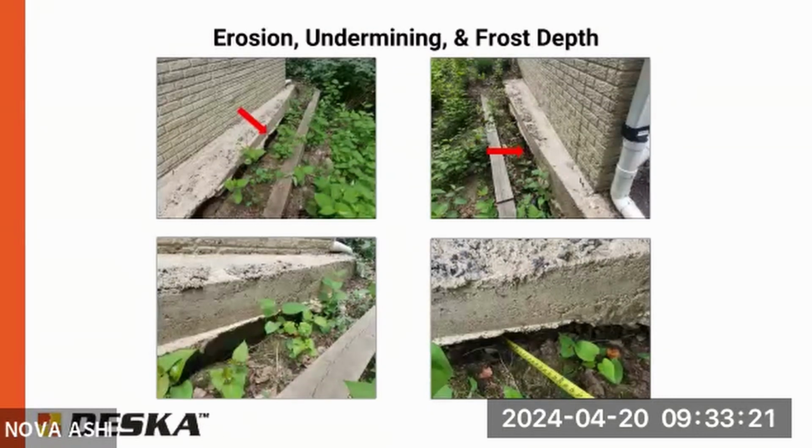The house is on a steep hill. And you can see the measuring tape here. I think it went in about 2 feet underneath that footing. And above that, you can see that's a poured concrete wall, which is extremely heavy. So this needed to have piers installed on it. And in this case, we had to install temporary helical piers on the footing.